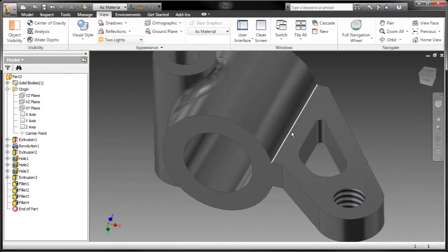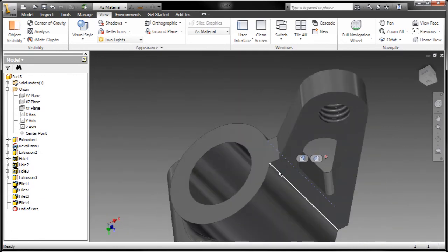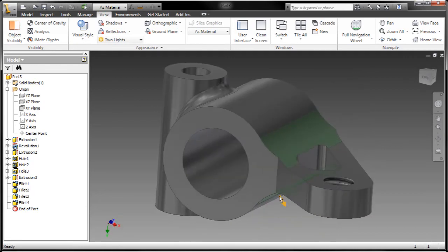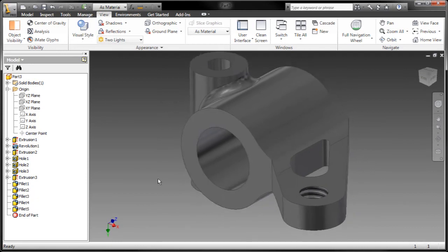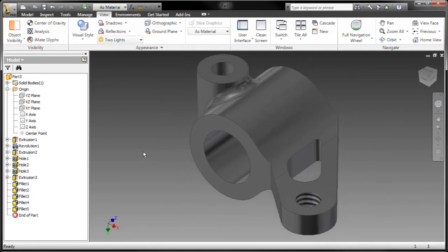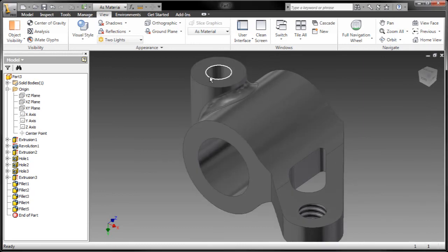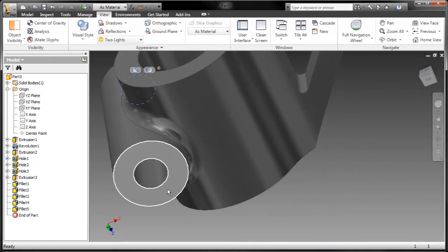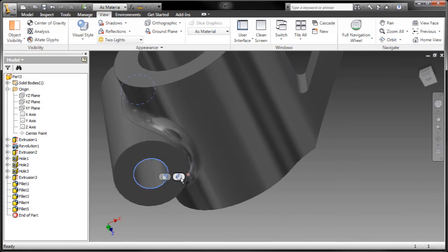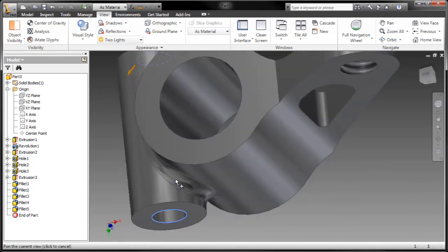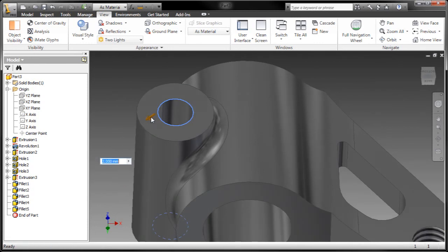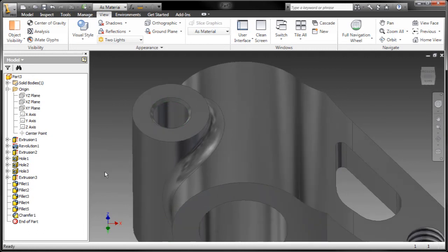All right, let's grab a couple more fillets here, and this particular fillet really shows off the new preview very nicely. Remember how it used to be just kind of a red arc? Well, now it's actually solving the fillet as you're going through those in real time, and gives you a real nice accurate preview of what's going to be calculated once you execute the command. Now I've been concentrating on fillets here. Let's not ignore chamfer. Chamfer works much the same way, only that you'll notice right underneath the length there, I have access to angle and distance, and here I'm just doing an equidistant chamfer.